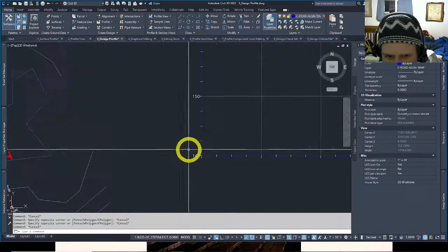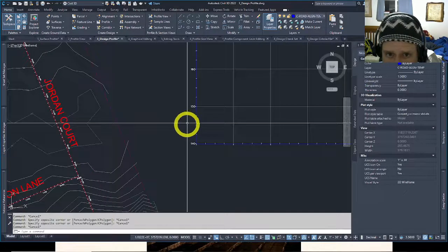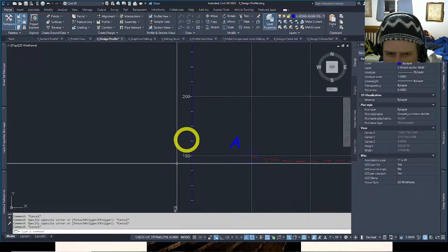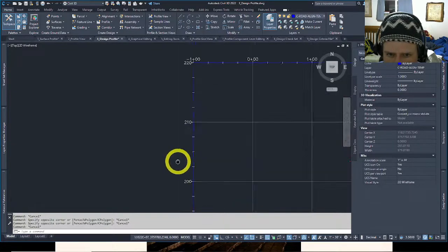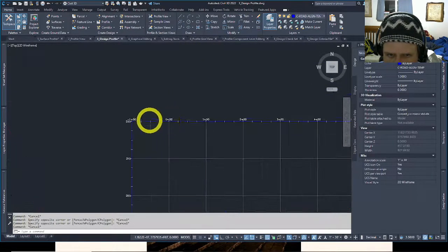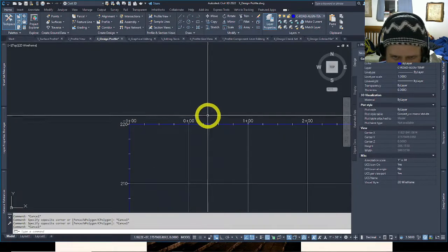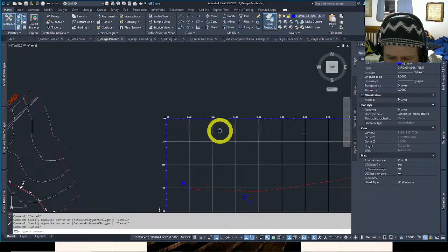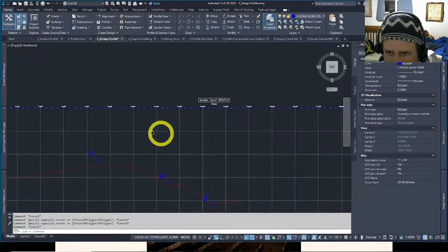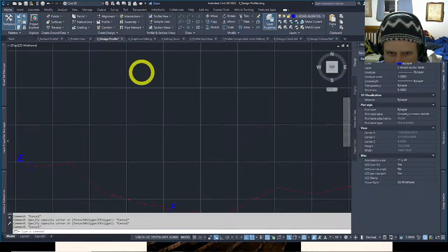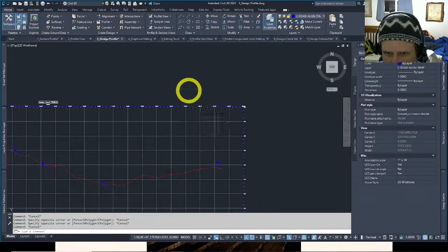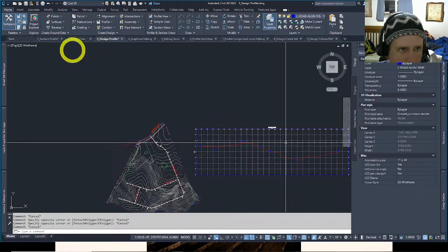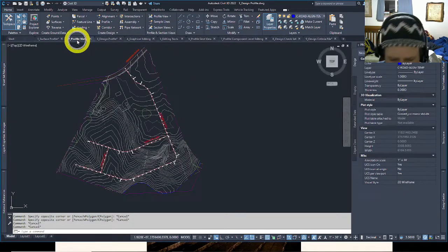And then the elevations in the Y direction, starting low, going higher. You can see it says elevation there. Depending on the profile view style is how it appears. Oh, here's our stationing on top actually. -100, here's 0, here's where the alignment starts. No surprise, that's where our profile starts. That's usually the case with these. They go together, Jordan Court profile. So the station in the X, the elevation in the Y. Go back to profile view drawing.